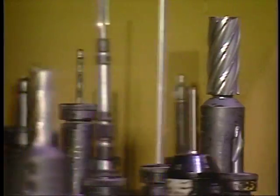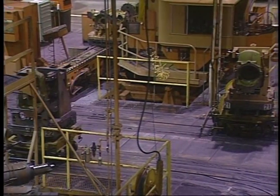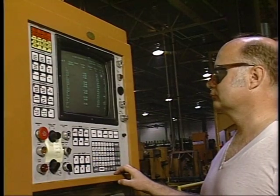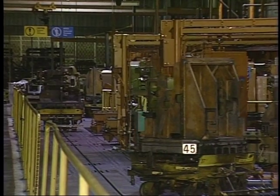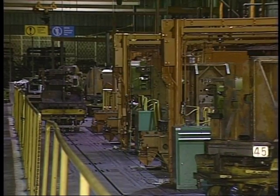Part programs and tool selection instructions are downloaded from the central computer to the machine center when the workpiece is delivered by the materials handling system. Once processing is completed, the machine center notifies the central computer, which then dispatches an AGV to pick up the workpiece and deliver it to the next station.